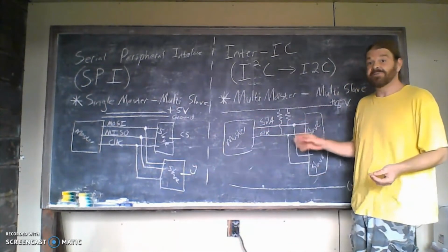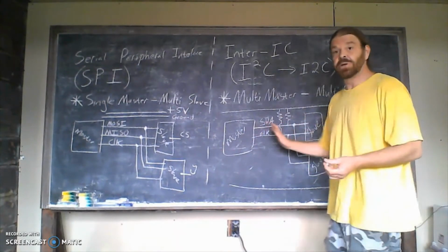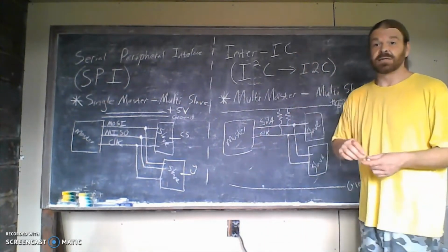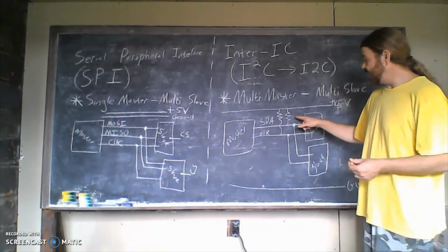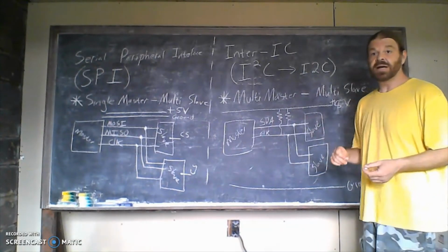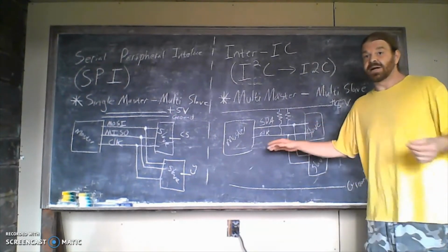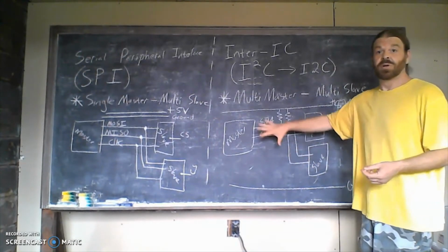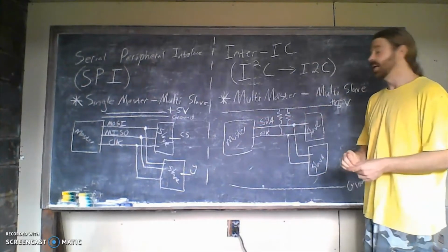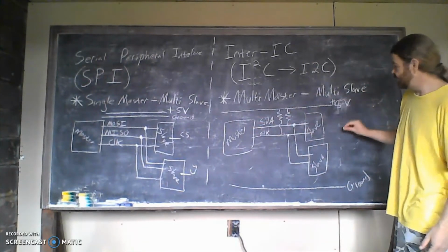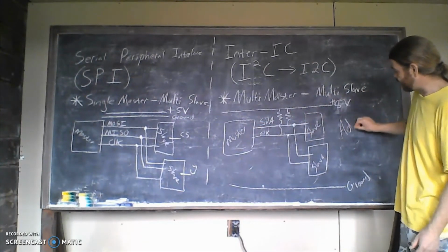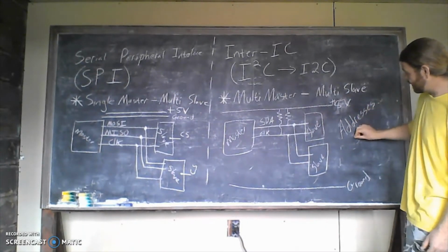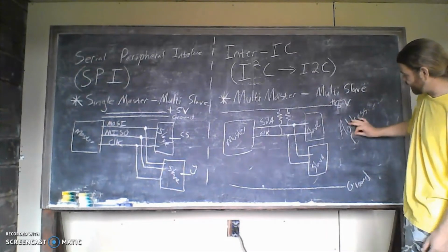There's not a definite high or low coming or going to any of the devices. This makes sure there will always be a high signal. And then as soon as something wants to communicate, the first thing it does is send out a low signal so that whenever the line drops low, everything knows to listen. And this one uses addresses. Address for each device.